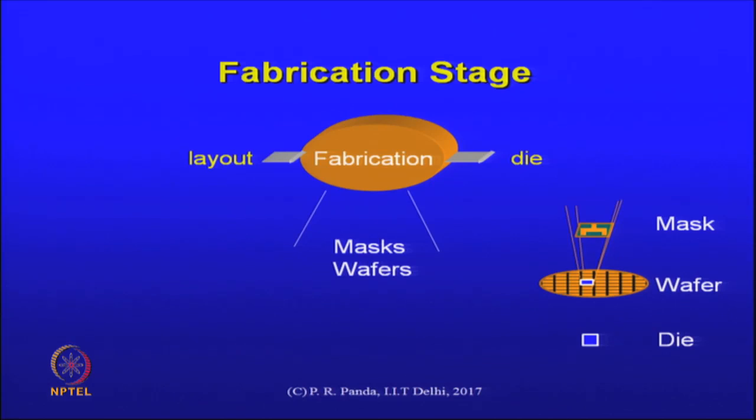That is design. Fabrication, again, if it were to be encapsulated in just one picture, it might be this: the input is a representation of what the geometry should look like, and that leads to a series of steps starting with the creation of a set of masks and resulting ultimately in wafers, which would be dissected into a set of dies that we are interested in.